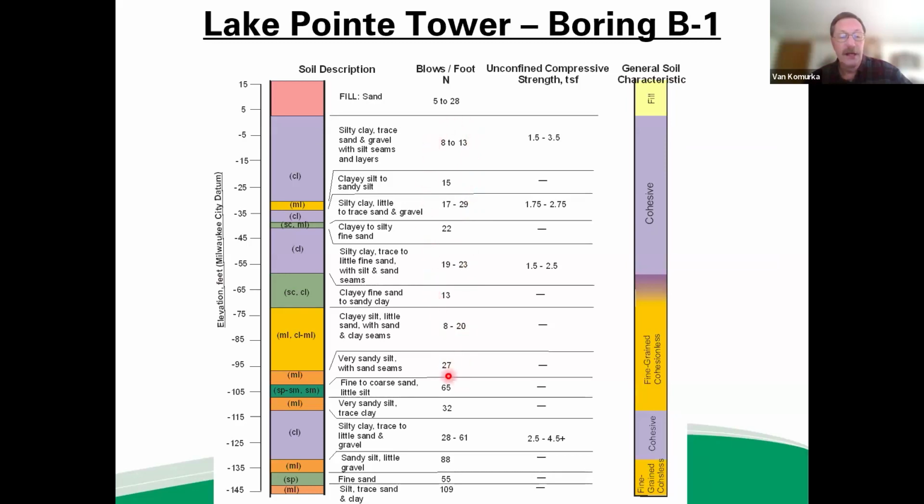Standard penetration blow counts. Down here at 105, we had a layer of fine to coarse sand where the blow counts jumped up, and we'll see the effect of that layer later in our results. Again, not very high blow counts until we get down to this till layer. And the unconfined compressive strengths of the clays aren't that stellar.